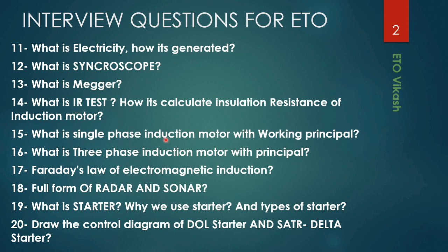Now, what is a single phase induction motor and its working principle? The single phase induction motor, as it is already used in the ceiling fan, is not self-starting. So to start, we are using a capacitor unit and something else. Without a capacitor also we can start, but we have to rotate the motor by hand. Initially we have to give it a direction to start, then it keeps rotating.